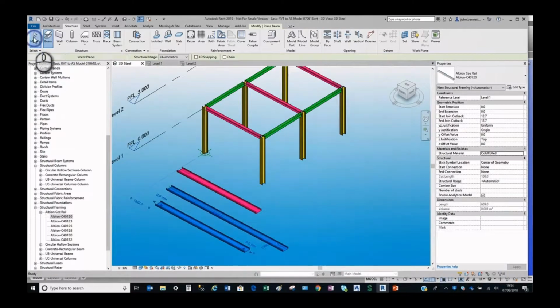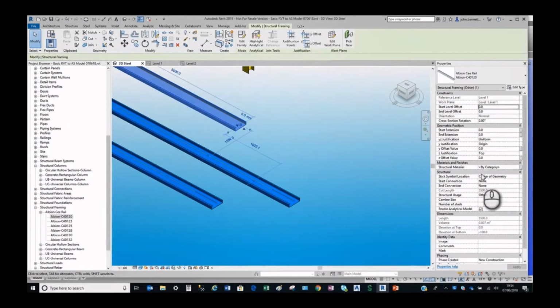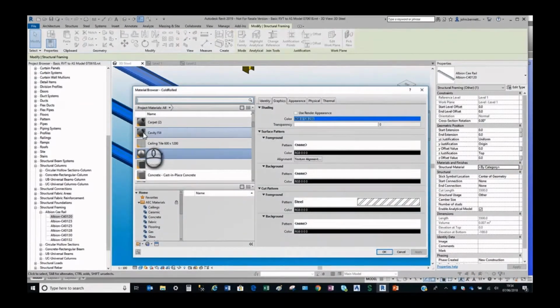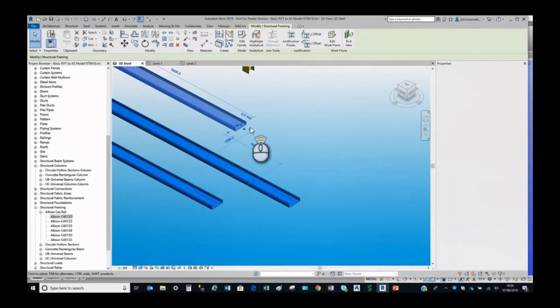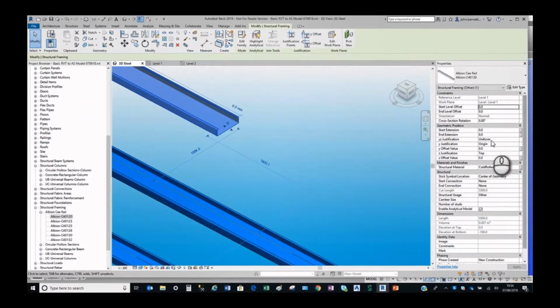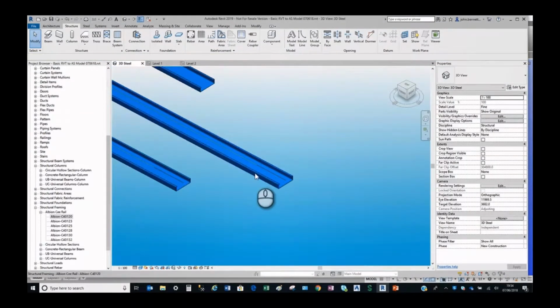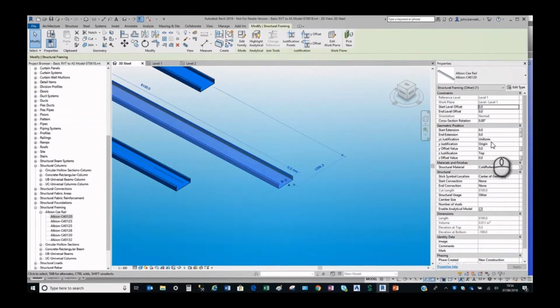So I've drawn the beams there. I'm just going to flip back and change this first beam, change its material if I remember correctly. Yeah, I think I do that. Another thing that comes into play is positions. In Advanced Steel, we're quite critical over our system line position. This can be changed under the structural framing position from the origin. You can move it. In Advanced Steel, it's quite critical for the system line position. It does affect things quite a bit from initial modeling to outputs.